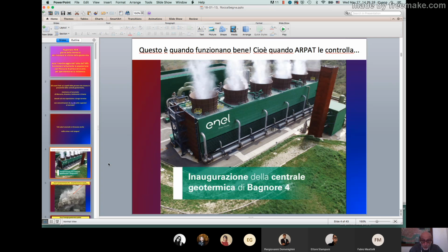Well, this is one of the recent geothermal power plants that was made, equipped with abatement of mercury. Actually, all plants at Amiata now have special equipment to abate mercury and H2S and ammonia, while the mercury abatement is done with active carbons, so it should actually remove about 80% of the mercury content in the fluid.